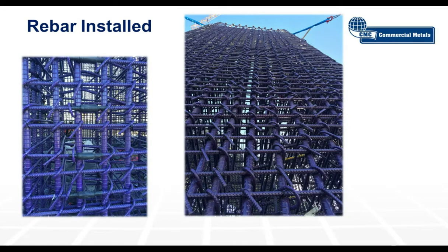Here's what the rebar looks like. This is the first lift, but going up this tower, it's going to look similar. All this rebar is epoxy coated with purple epoxy. You can see the HRC couplers in the smaller view there. It's shrink wrapped to protect the couplers from rust. You also see all those little J-hook ties, it's 100%. Every intersection is tied up. In the section that we're modeling above, where the anchor box is, it's 50%. It's not 100% tied up like that.